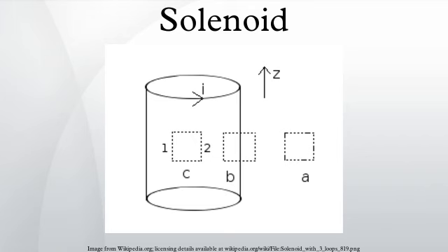Electromechanical solenoids are commonly seen in electronic paintball markers, pinball machines, dot matrix printers and fuel injectors. Rotary solenoid. The rotary solenoid is an electromechanical device used to rotate a ratcheting mechanism when power is applied. These were used in the 1950s for rotary snap switch automation in electromechanical controls. Repeated actuation of the rotary solenoid advances the snap switch forward one position. Two rotary actuators on opposite ends of the rotary snap switch shaft can advance or reverse the switch position.